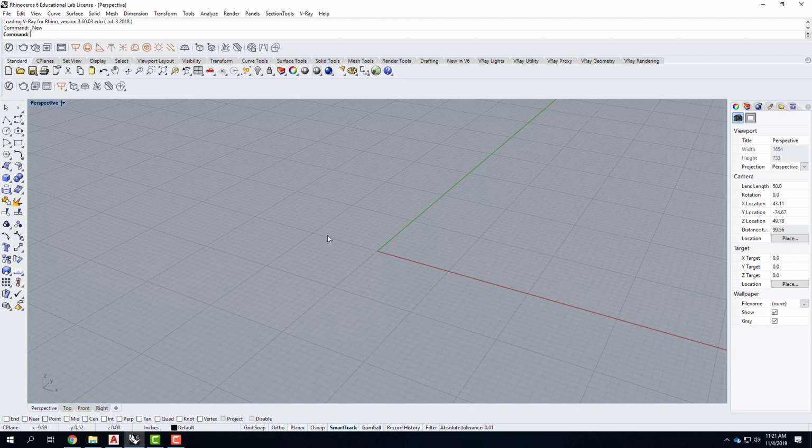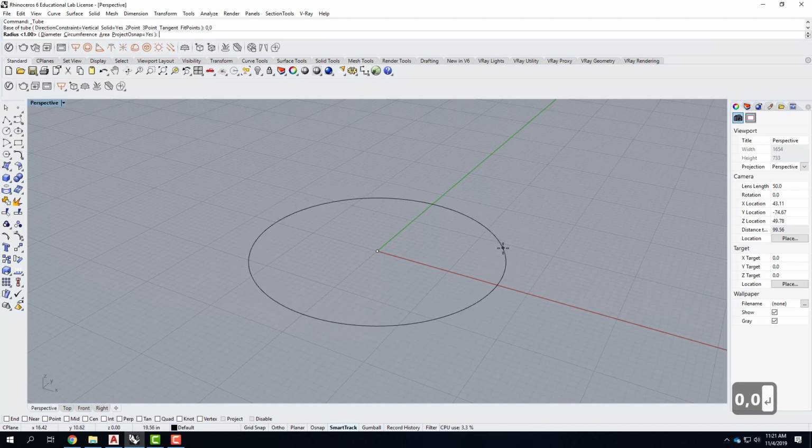So the first one that I'm going to do is a recessed light in the ceiling, and I'll do a round one, like a can light. So nothing particularly fancy, it would be recessed, it would be up on the ceiling, etc. So I need to make the geometry that holds the light first. If I think about that, I could start with one of my standard primitives here. I'm going to use this one, which is the tube setup. I'll click on that. I'm going to start with my tube at 0, 0. There it is. It's going to ask me the radius, the outer radius. So let's say this is a 6-inch can light, so my radius would be 3 inches.